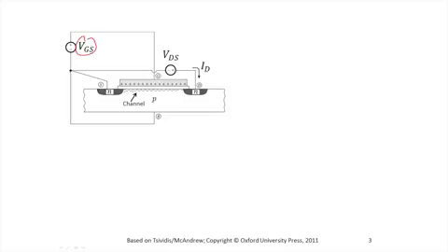And if VGS is large enough, positive charges accumulate on the gate, as you see here. These positive charges attract negative charges consisting of electrons below the insulator. So now you have an N-type region which has plenty of electrons, you have another region in the channel which has plenty of electrons, and finally a drain region with plenty of electrons. So this has formed a bridge between the source and the drain, and current can flow.